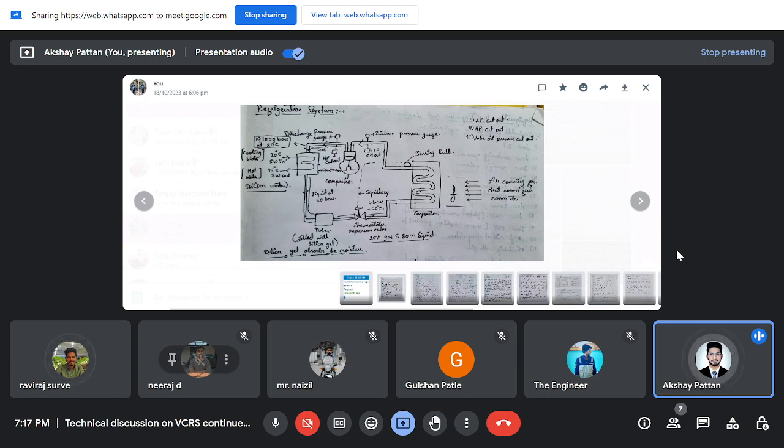Sorry, low lube oil pressure cutout, right? Yeah, right. If it was a splash lubrication, then there is no meaning in putting that low lube oil pressure cutout. So obviously, there is a pump inside, or there is a device which is regulating the flow of lube oil. Obviously, it might be used. Yes, got it.